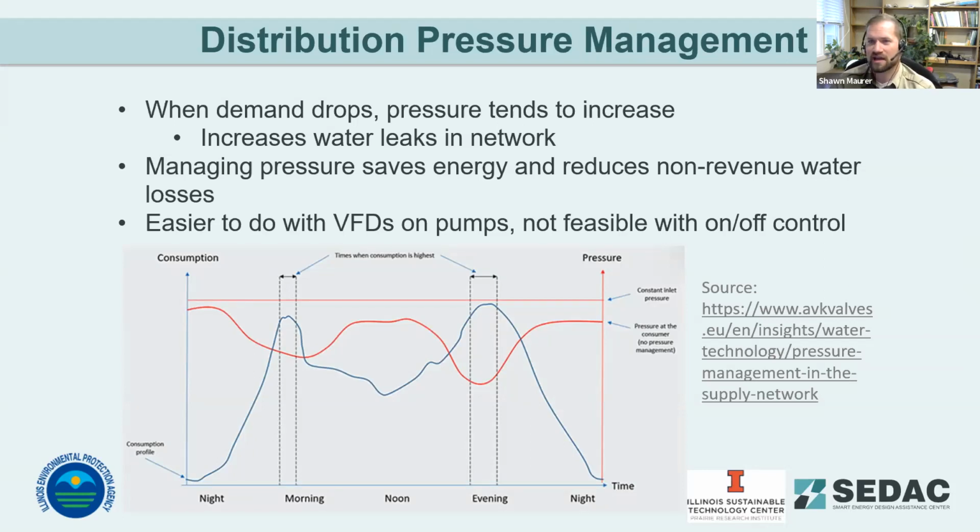And a lot of this filtration backwash technology also applies to wastewater plants. We're seeing a lot of plants moving to cloth media filtration, but managing that backwash cycle and reducing how much backwash water you're moving through that wastewater system is some significant energy savings for wastewater as well.